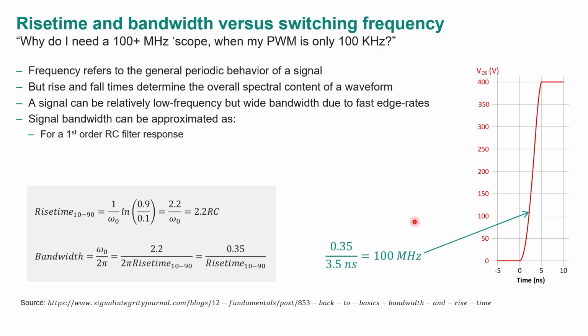The lesson here is don't use a 100 megahertz scope. 200 is barely adequate. I've seen gate ringing signals at 400 megahertz. So 500 megahertz is the minimum. I'd recommend a 1 gigahertz scope, and that includes the probes that go with it.